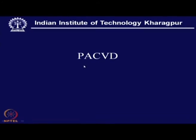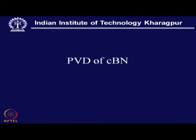So, during that process, if we have in a controlled manner, even in this CVD process, if we have a controlled manner ion impingement, in that case definitely there will be a gain in the quality of the coating. So, this is exactly PACVD what we have seen. Now, this is also very important, PVD of CBN. We know that diamond and CBN, these are called super hard material.